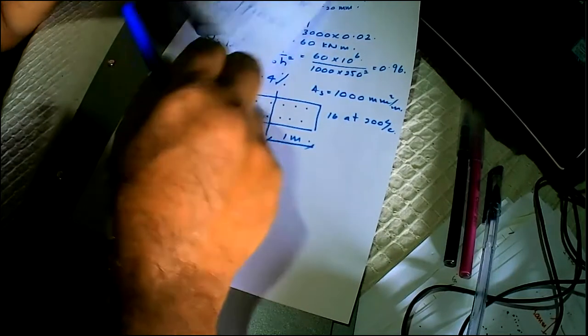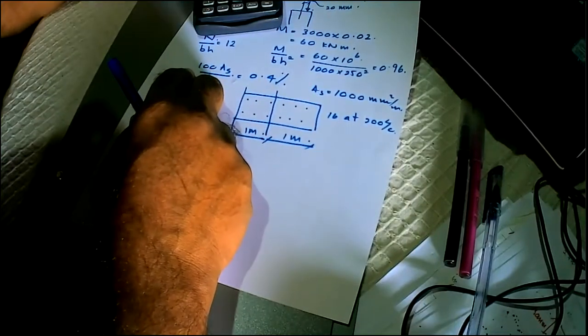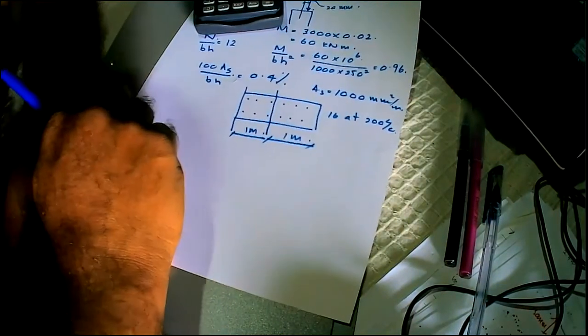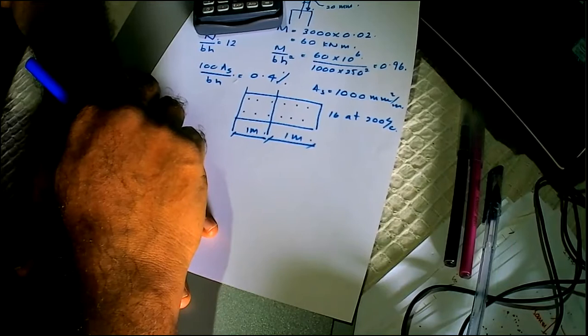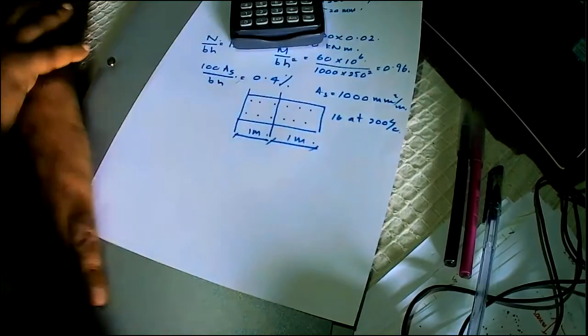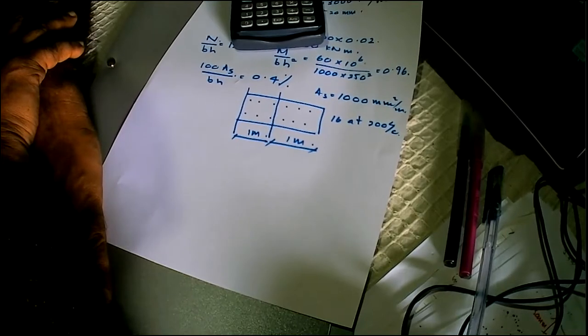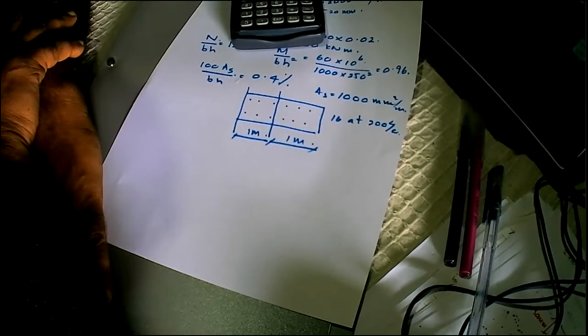So if tension occurs on that one side, what do we have to do? Yeah, if tension occurs, that means the wall will be cracked. Is that right? If tension occurs, we'll have a problem, because that tension will be transferred onto the foundation. Generally the piles are designed to carry axial load, vertical load, or the compressive load. But if tension can occur under the shear wall, then it's not a very healthy situation.